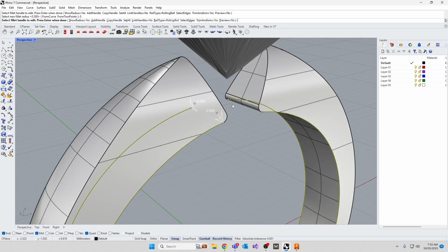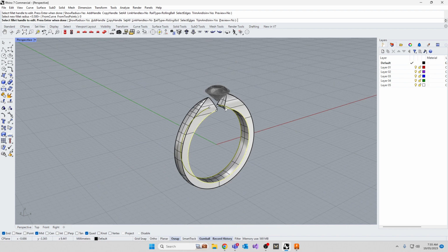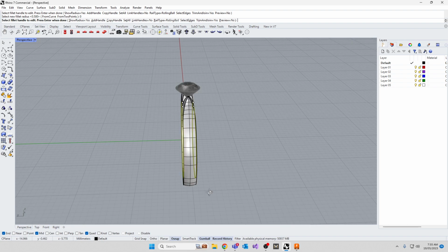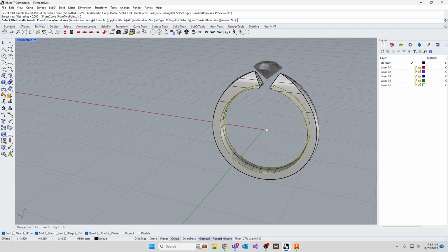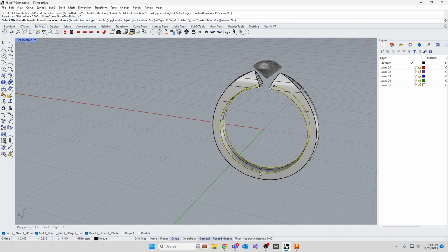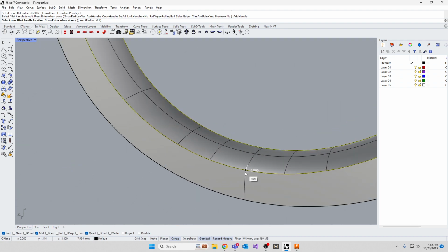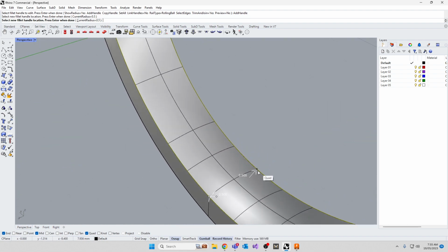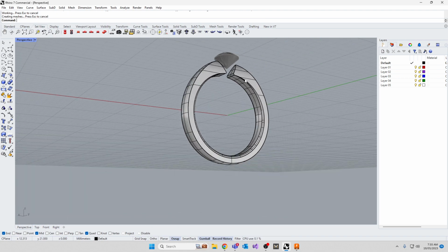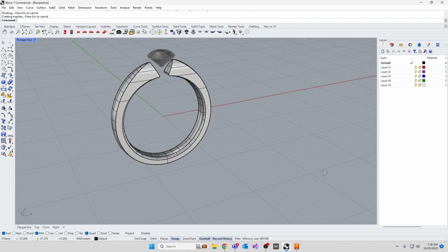I'm repeating this because it was a little bit confusing in the last lesson, right? So again there, and again there. Okay. So we're going from no fillet to a 0.5 millimeter fillet back to a full fillet. Except that we only had 2 fillet points. You can see at the bottom here we've got nothing. All right? So we want to add a handle down the bottom here, and want to add another handle down the bottom here. Okay. And so now when we press enter, we've got our fillet going from nothing to 0.5 back to nothing. Got it. On both ends. All right.